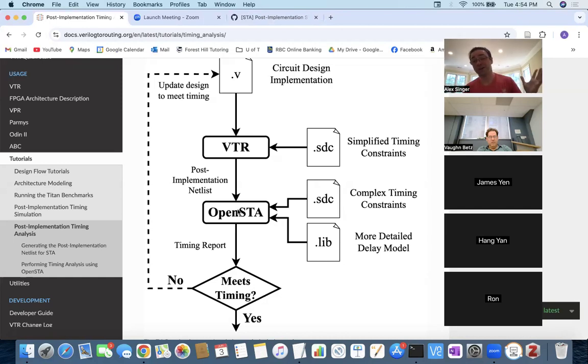Also, what if it's hot outside and you want to run your FPGA? Now your delay model changes because it's hotter, things might run a bit slower. Delays are supposed to change, and you're supposed to take that into consideration. Your max delay analysis should include how hot this chip could ever get. Sometimes people don't do that, but that's risky.